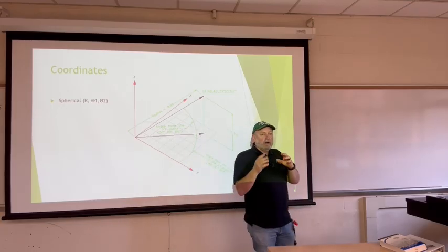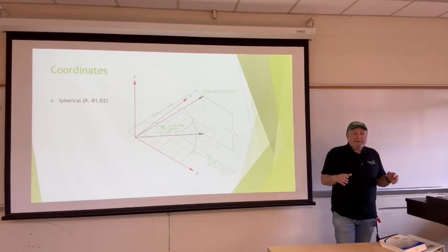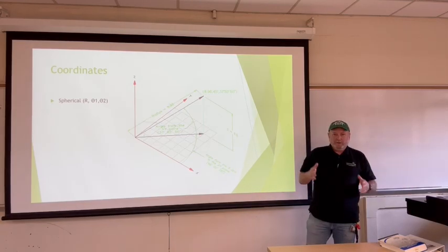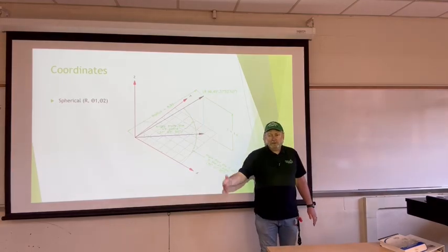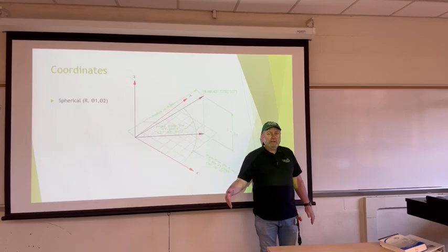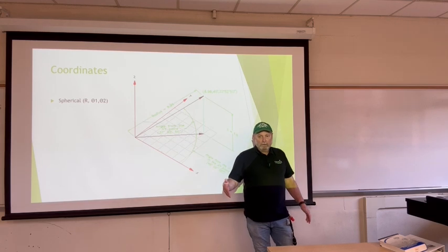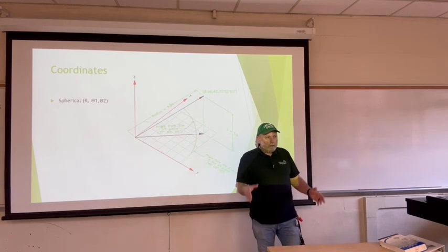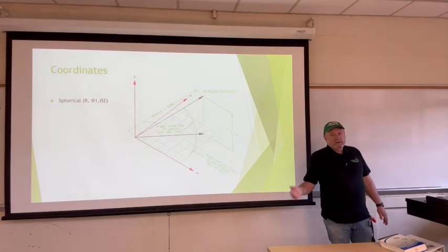So we're going to need to be aware of the time component, and that's kicking me down a rabbit hole here in another class that we get into a lot more. But the time is going to be critical, so we know this was 37 degrees at this time using this specific datum. Now we are here at this time with this datum, and now we're saying that it's going to be this. That spot didn't actually move. It's still there. The coordinate values we place on it are going to change every few years now, moving forward.